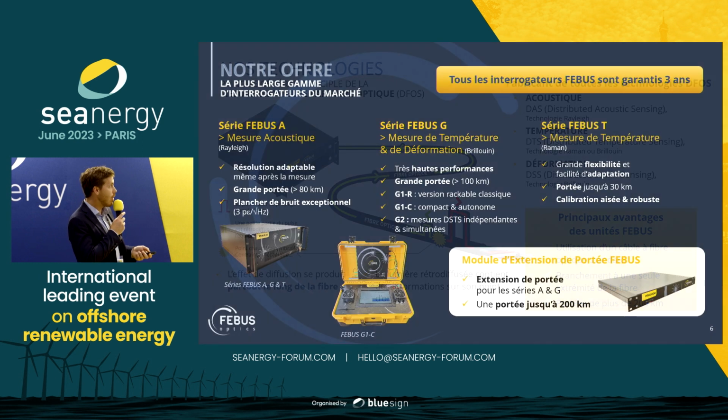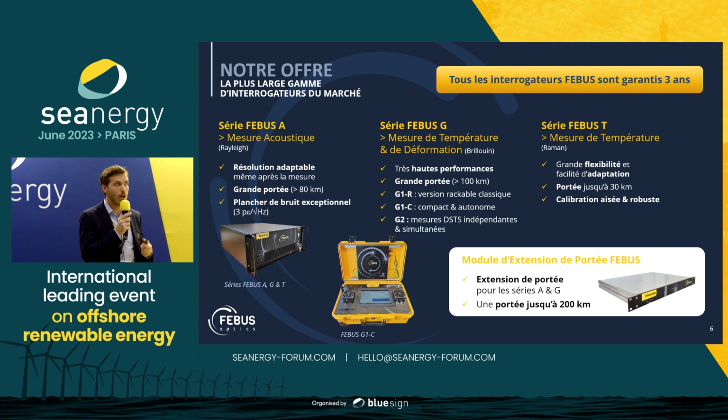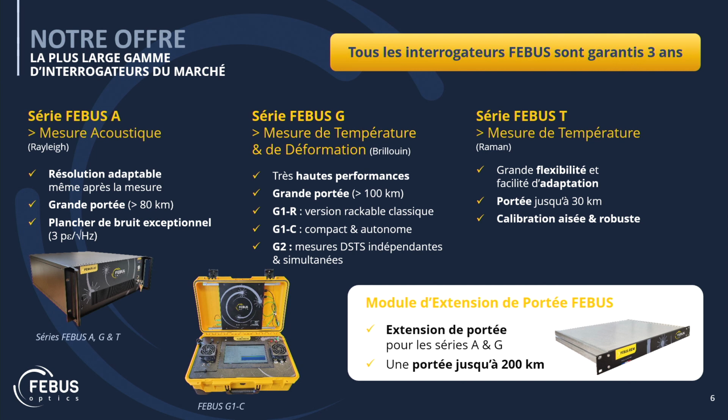At FEBUS, we took the approach of developing all the technologies available today on the market to make measurements on fiber optics. That means being able to use a relay system to acquire acoustics, what we call DAS, that will give us a very long range, more than 80 kilometers, at a very low noise level, so we can detect extremely small things. Here it says 3 picostrains. That means that if you speak a bit loud next to an optical fiber, we're able to hear you.